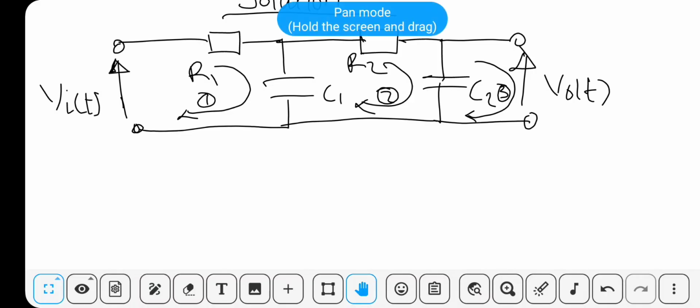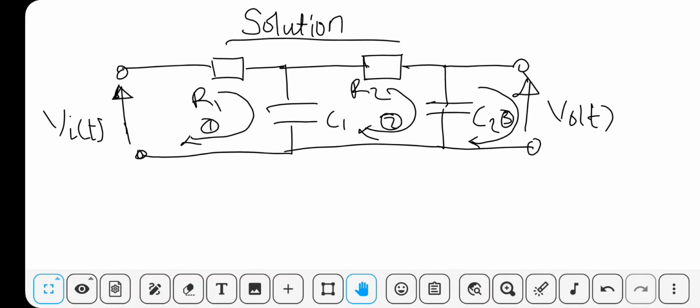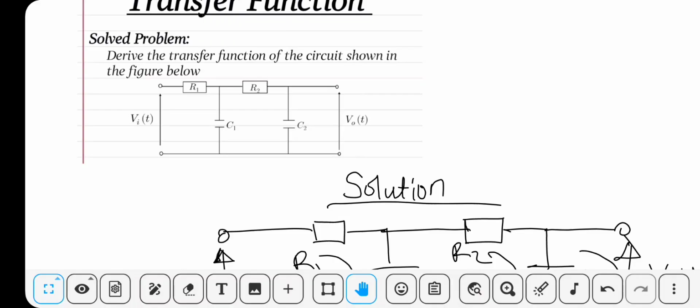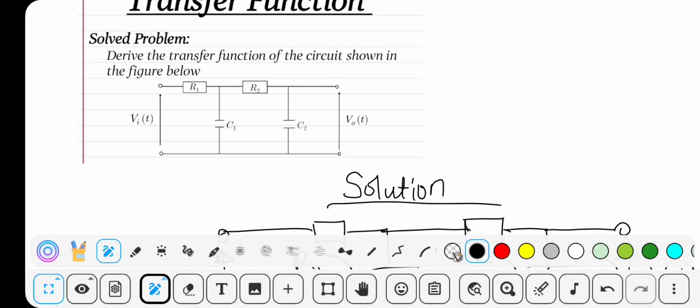Note that for any given circuit, if the input is drawn to be open, there is assumed to be an ideal voltage there, so it's not an open circuit. But if the output is open, it is assumed to be an open circuit, so the current flowing here is 0, which is I3.